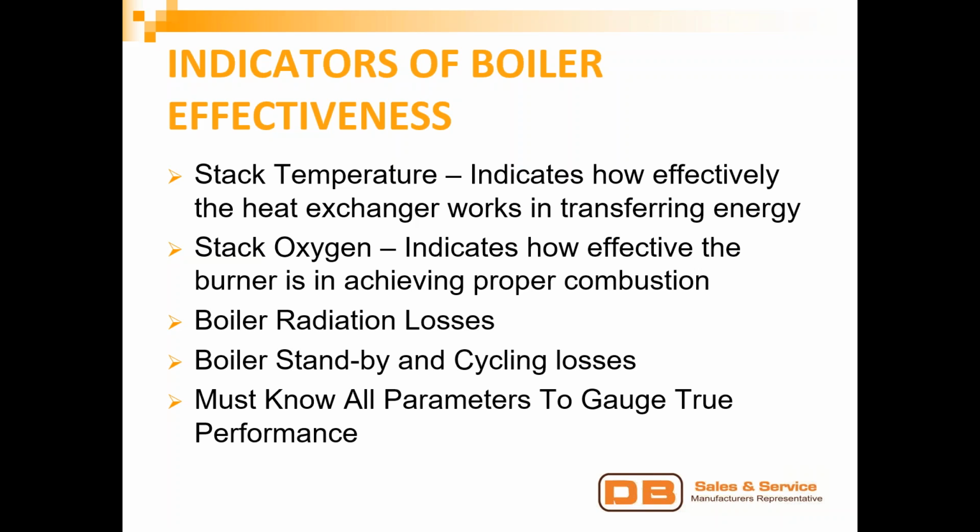And you also have boiler radiation losses, boiler standby and cycling losses. Every time the boiler fires up, it has to go through what's called a pre-combustion purge. Then when it's done firing, it has to go through a post-combustion purge, meaning that you're taking room temperature air, running that over the heat exchanger, and sending that out the stack. You actually start to pull heat away from the loop, your hydronic loop, or from your steam system every time you're doing one of those purges. So those cycling losses can add up. And you must really know all parameters to gauge true performance.